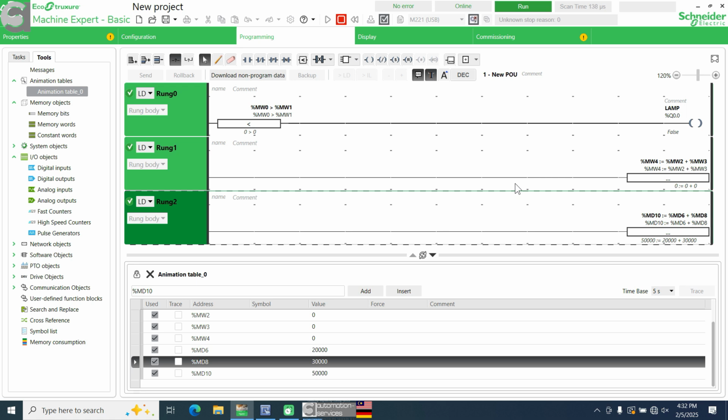Just now the DO is what? Digital output. Because the heating coil just turns on and off only, to heat the coil. So it's just a digital output. If you want to control a valve, then it's an analog output. Tomorrow we can see your wiring diagram as well, so we can understand better.